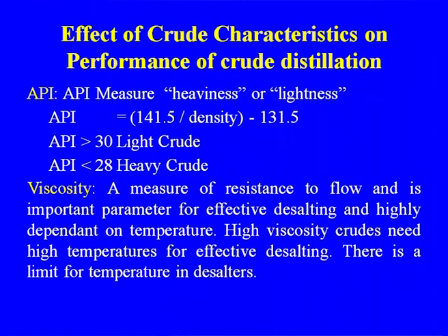There is a limit for the temperature in the desalter, because if you go beyond it, the separation efficiency in the desalter will go down. So, this is why viscosity or API is very important in the desalting process, because desalting you cannot look at separately from the atmospheric distillation unit.